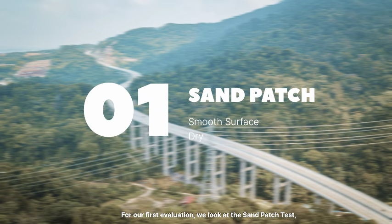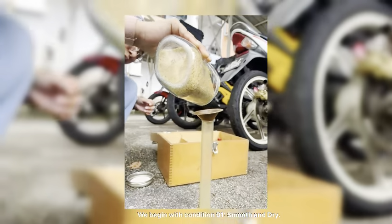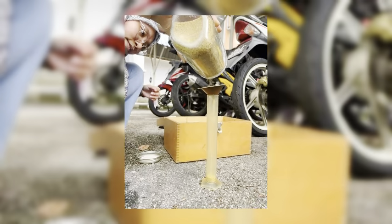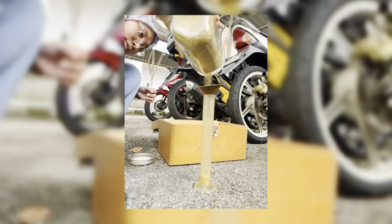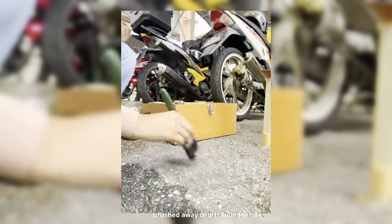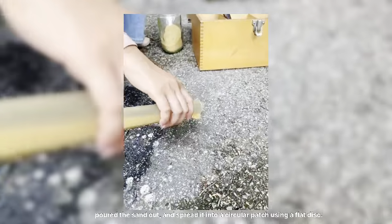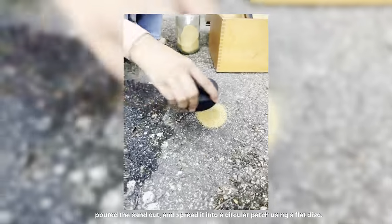Our evaluation will look at the sand patch test, which measures pavement macro texture depth. We begin with the condition smooth and dry. We carefully pour a known volume of standardized sand into our cylinder. Brush away the debris from the side. Pour the sand out and spread it into a circular patch using a flat disc.